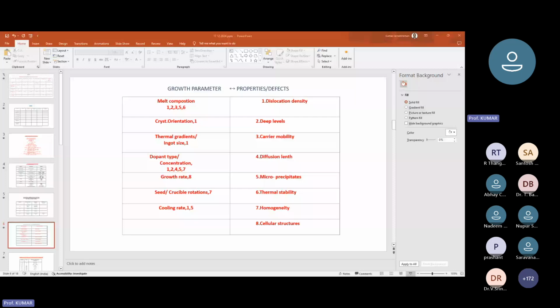As you can see, we need to raise the temperature in some cases up to 3500 degrees centigrade. Normally, we can go up to 1500 degrees centigrade, or in the range of something like 1000 to 1500 degrees centigrade, depending on the type of material. And you see, resistance heating one can achieve through carbon as a heating element up to 3500 degrees centigrade. And the advantage is it is very simple and versatile.